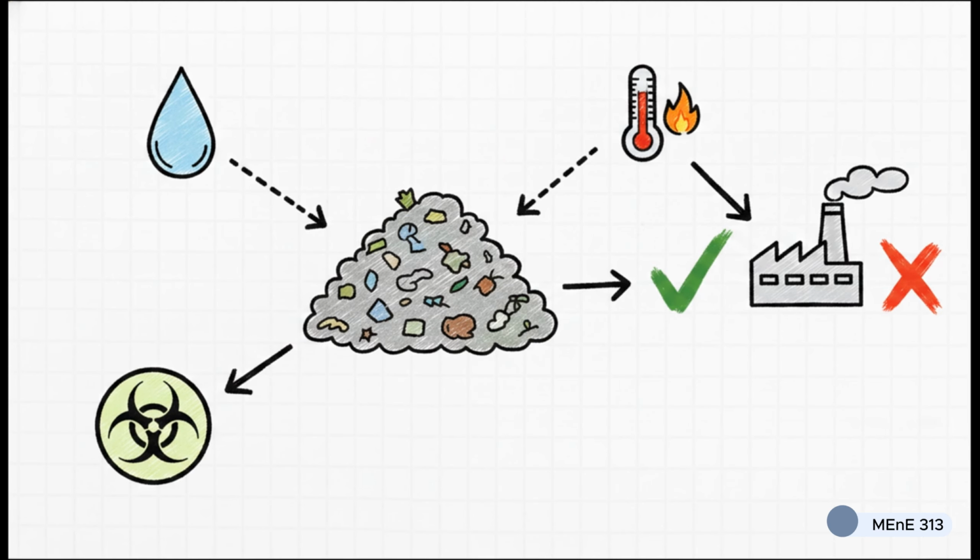direct combustion process, but it could be absolutely perfect for a biological one. The heating value tells you if you can actually recover useful thermal energy at all. And things like contaminants, chlorine, heavy metals, those are going to dictate your air pollution control costs. Your feedstock's properties basically make the big engineering decisions for you.